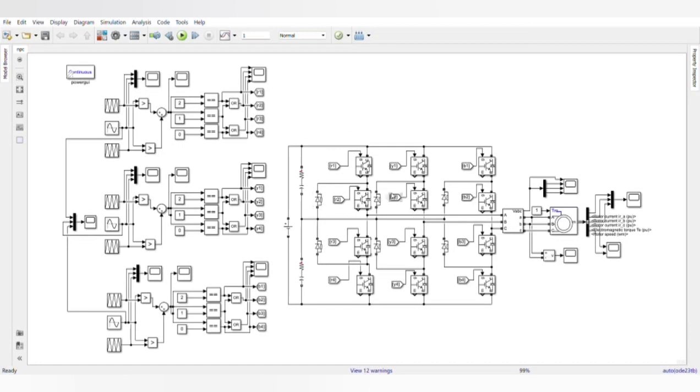The main circuit consists of a DC voltage source block, which is used to produce the output voltage, and a series RLC branch, which is used as the RC filter to reduce the harmonics in the generator. R1, R2, R3, R4 are the From blocks, which are used to access the signals from the go-to blocks.